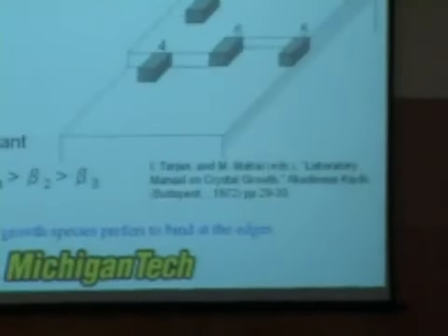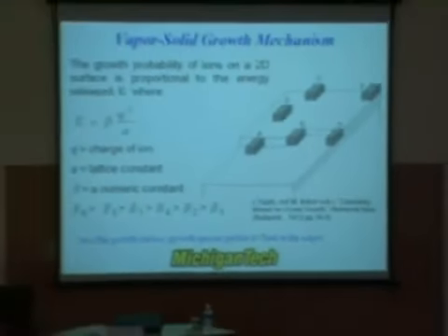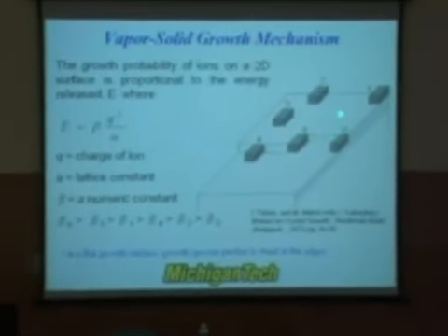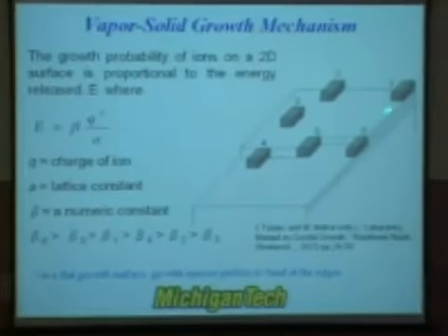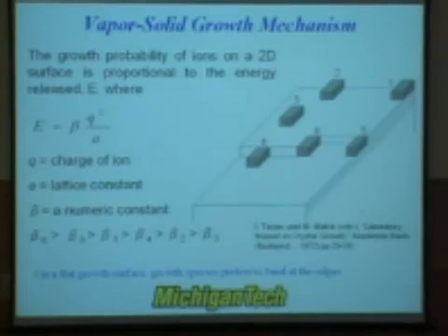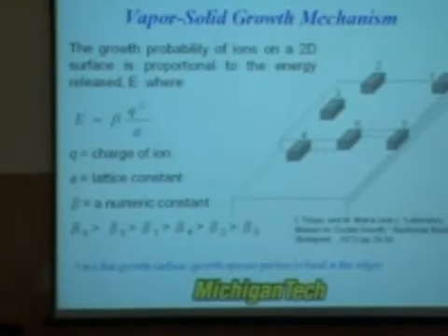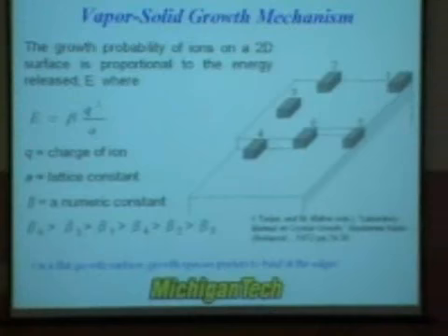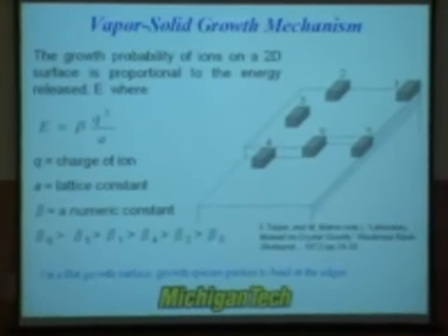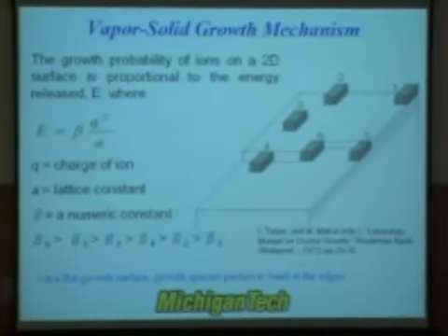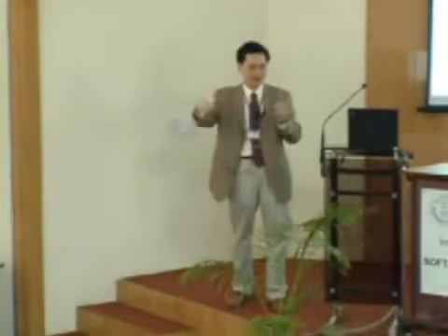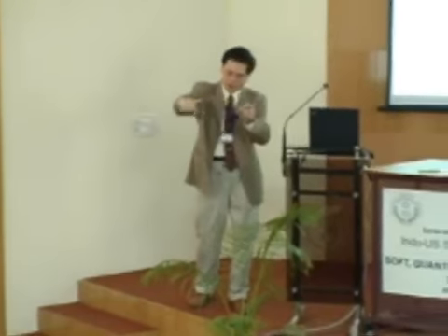And at the same time, if you look at the nucleation theory, you find that if you have a perfect atomic surface like this, you have only 1, 2, 3 possibilities for the atom to land on the surface. And you will see that number 1 and 2 are the preferential sites for growth. So which means if you can cool down your growth conditions so that there is no growth at the center of the rod, they will confine the growth at the edges, just like what I show here, right?